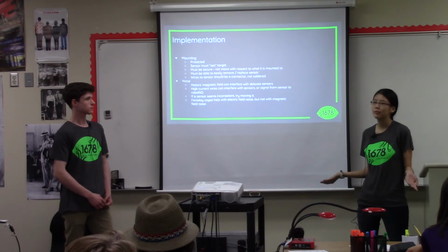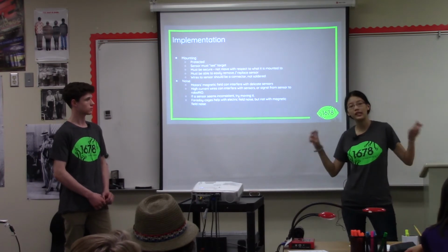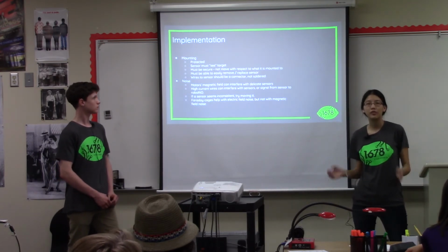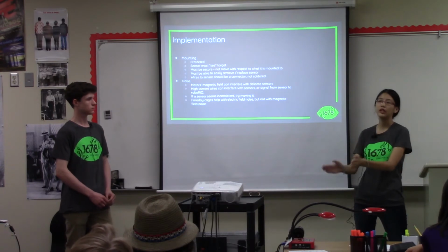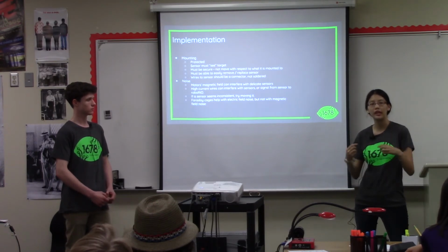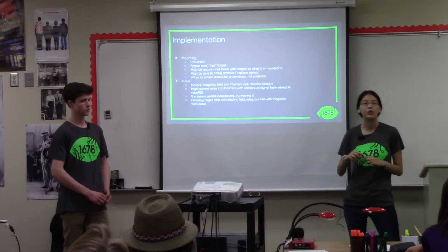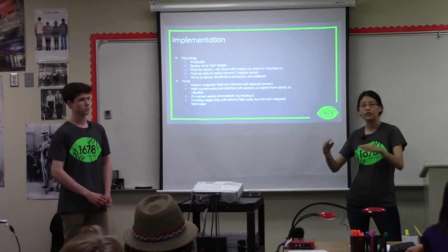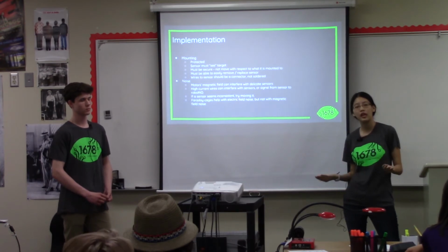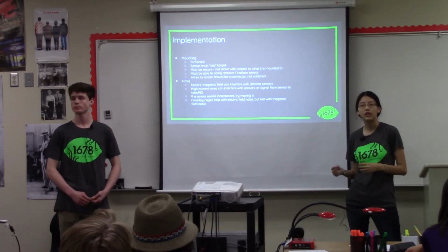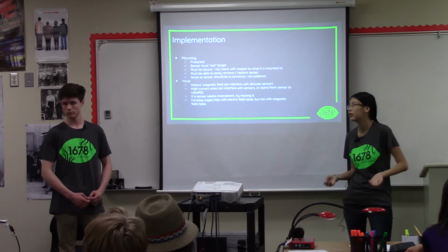One obvious fact about sensors is that they must be able to see the target. For example, if you're using vision, you need both an LED to shoot the light and the camera to take in the light. Both of those must be within line of sight of the reflective tape on the goal. Or else you could get interference from the field piling up in front of the light, and that will often give you mixed signals and not allow your vision to function properly.